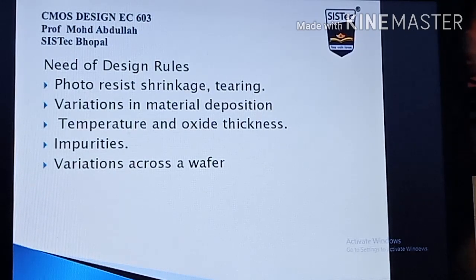Or there is the tearing part: if some part of the N-well or P-well tears out, then it is called tearing. So we need an exact rule to have a certain predefined area for the designing of the photoresist area and for the removal by etching.